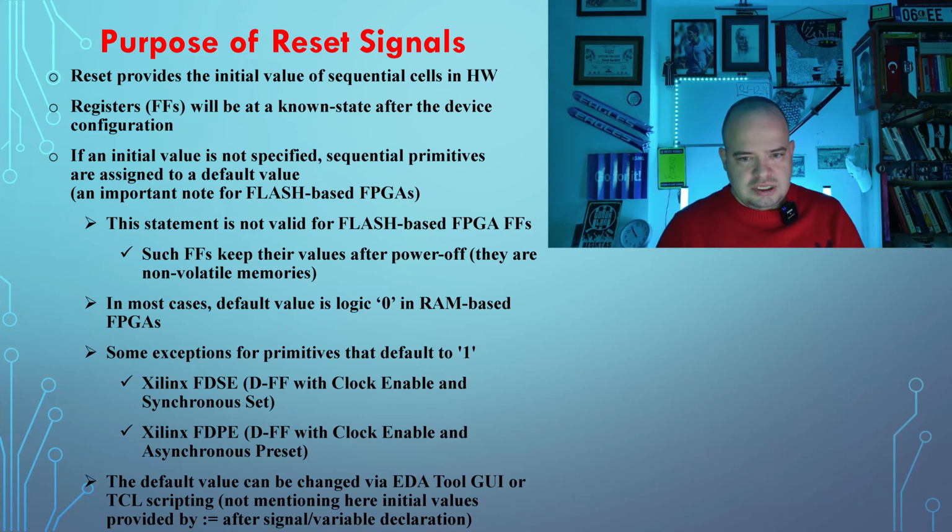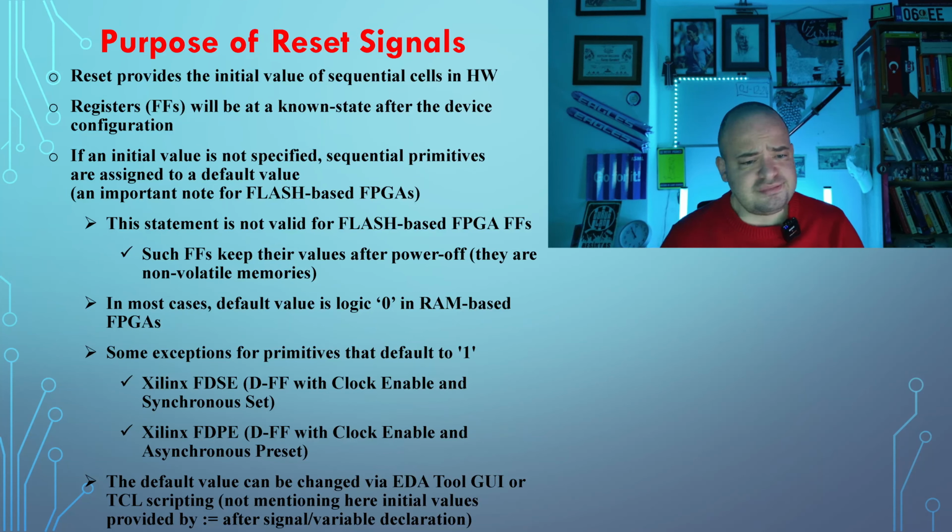In most cases for RAM-based FPGAs, that default value is logic 0. But there are some exceptions, some primitives. You can find more details in each family's guidelines.